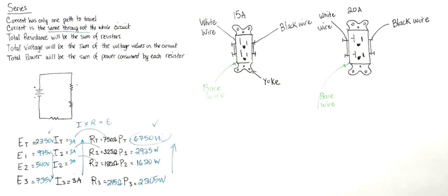Because most of our tools are insulated, but I'm going to show you that the tools we have here in the class, even though they're insulated, are not rated for live circuits. So if you are actually going to be working with live circuits, you have to invest hundreds of dollars to buy tools that are actually rated for the voltage that you're going to be using.